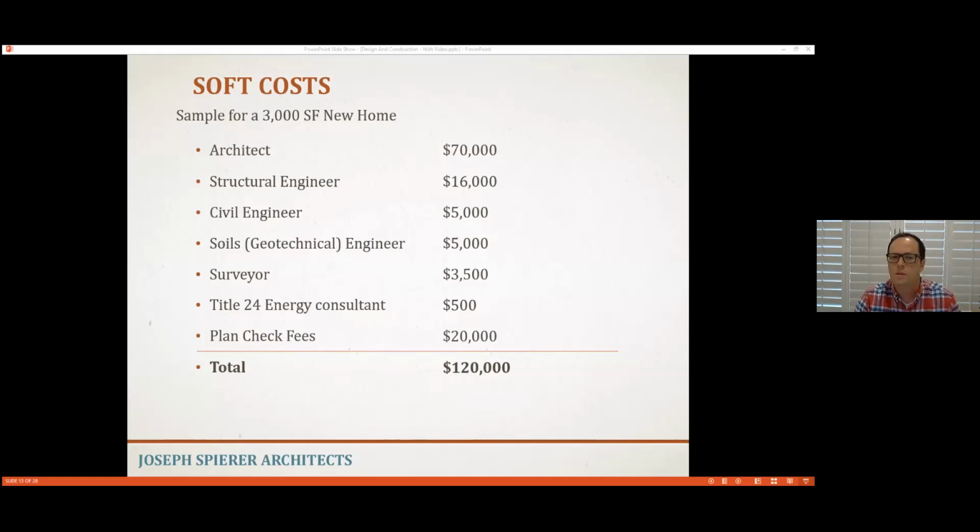If we hadn't consulted with a soils engineer at the beginning of that process, we would not have known what type of soil we're dealing with, and therefore we would not have known that we needed 120-foot deep caissons, that's concrete and steel, straight into the ground. That's 120 feet, that's 12 stories under the ground to hold up a single-story house. The client wanted it badly, so they ended up closing anyway and moving forward.